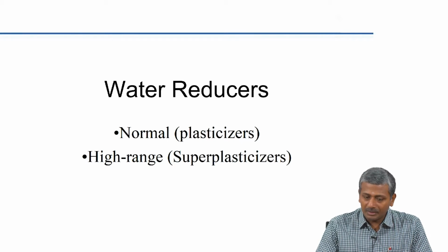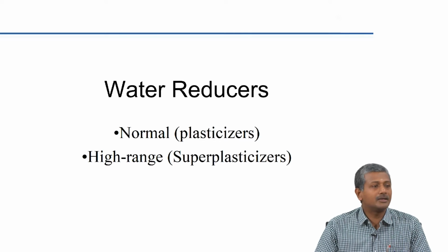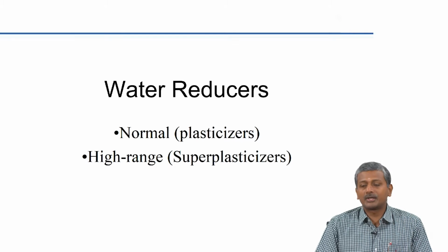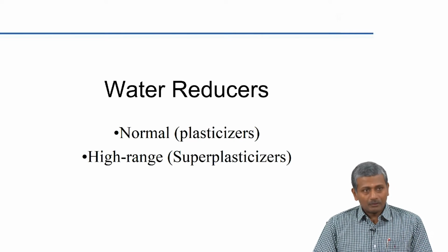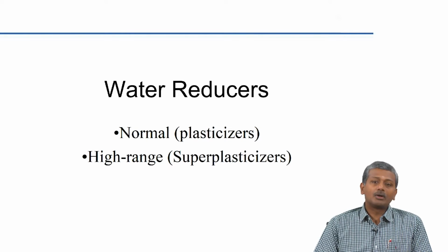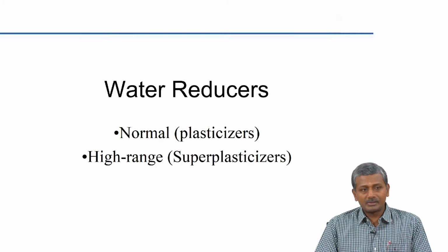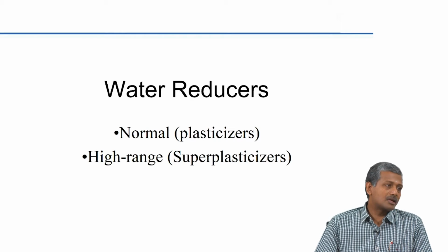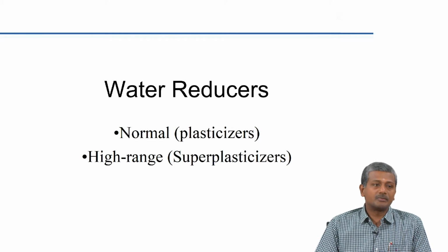Okay, so what does it mean? What does water reduction mean? Any idea? What is the meaning of water reduction? What water are you reducing? The water required for a certain workability in concrete can be reduced by the use of these chemicals, and as a result what happens? The strength and durability will go up because the water to cement ratio is reduced.